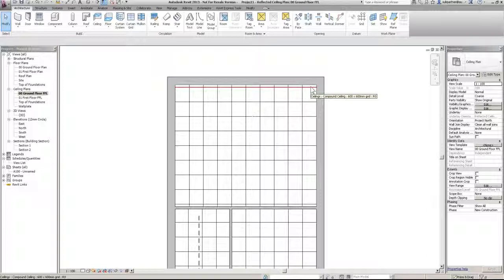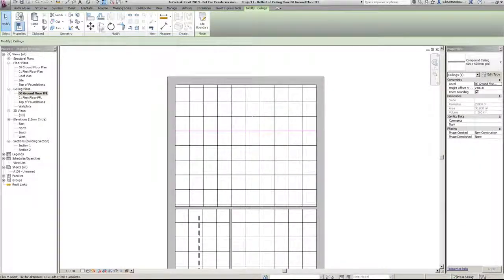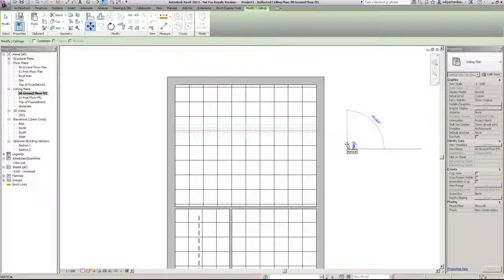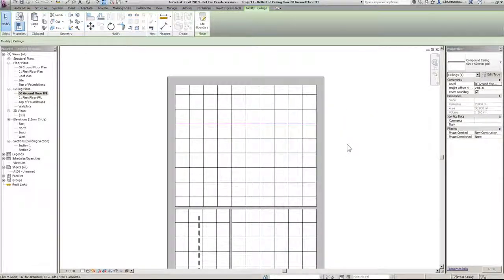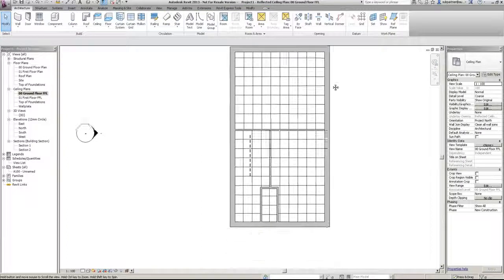Now what I'm going to do, I always teach people to create things in their BIM model how you're going to do it in the real world. So in the real world, if you've got a silly little cut across there, your entire grid system would move half a tile. So that's exactly what we do. But we don't move half a tile. We pick one of the lines involved in the tile, move from here, go up 300, which is half a tile, done. And the rest of the grid will just basically align to it.